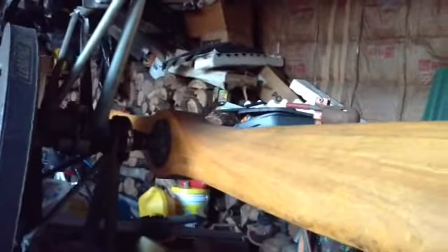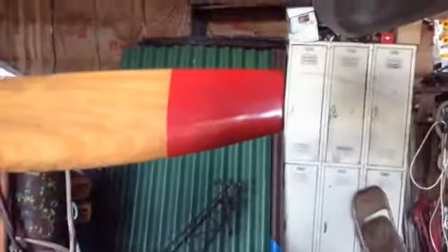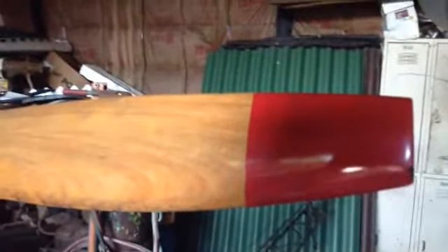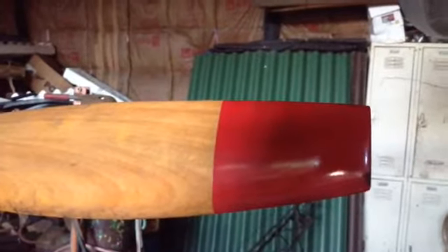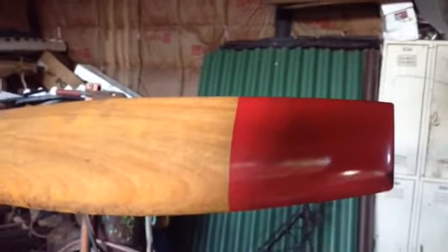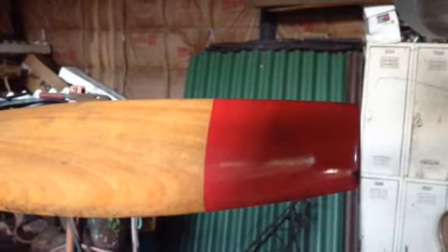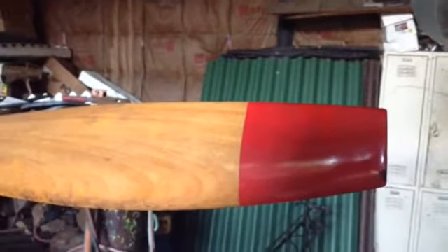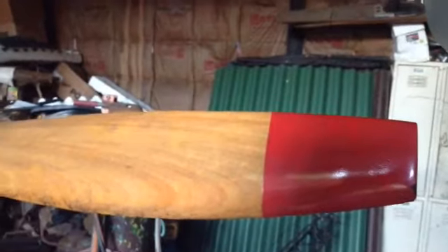Okay, according to the ultralightnews.ca website, a 60 by 30 wooden propeller built by Tennessee Propellers, that's what this is. See, it's 60 inches from that tip to the other tip, which means a 30-inch radius. And that 30 number means when that tip goes around in a whole circle, at a 0-degree angle of attack, it will go 30 inches forward. Airplanes don't really go 30 inches every revolution. They generally go about 79% of that, but that's what that 30 means. That's the pitch distance.